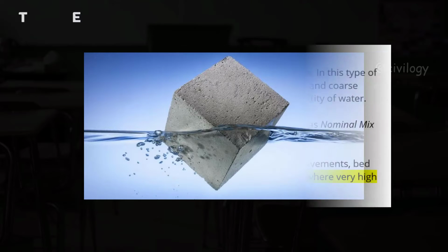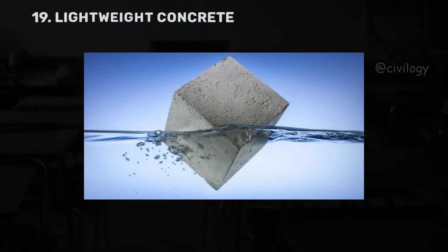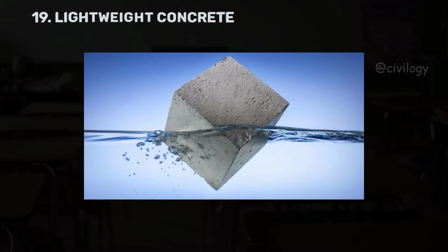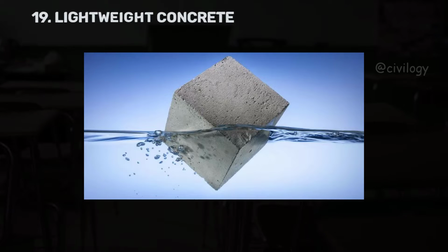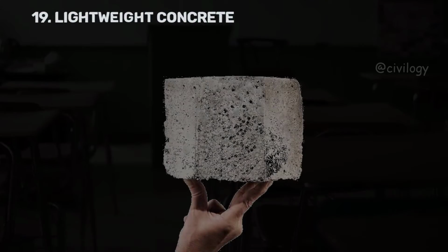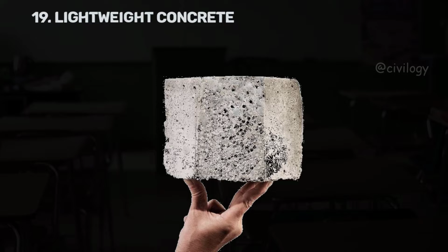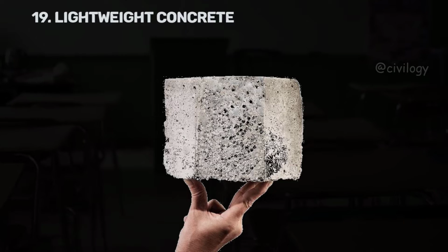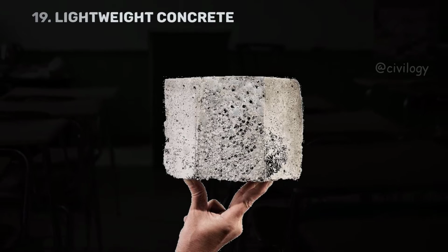And so next, lightweight concrete. Any type of concrete having a density less than 1920 kg per meter cube is classified as lightweight concrete. Various types of aggregates that are used in the manufacturing of lightweight concrete include natural materials and also artificial materials. The single important property of lightweight concrete is its very low thermal conductivity. Lightweight concretes are used depending upon their composition for thermal insulation, for protecting steel structures, and they are also used in long span decks and even as building blocks. So these are the main importance of lightweight concrete.